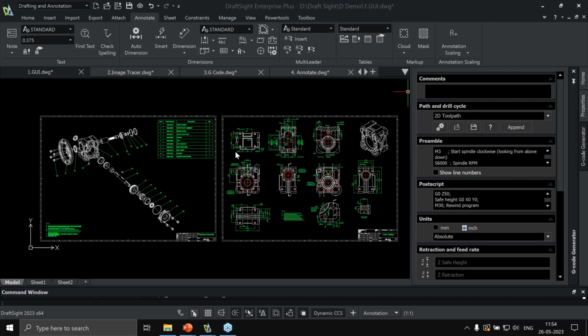There is a question from Mithun. Can we convert a SolidWorks 3D model to 2D in DraftSight, and with annotation, can we make changes in 2D or not? For this, the SolidWorks 3D model should first be saved as a .sat file, and then that file should be imported in DraftSight. With the help of DraftSight layout space, in 3D modeling, as I showed you, there are view configurations, where you can create front view, top view, and place them in different orientations in the drawing sheet. Later you need to manually provide the dimensions. There are no automatic dimensions available. You need to manually provide the dimensions for each individual view.